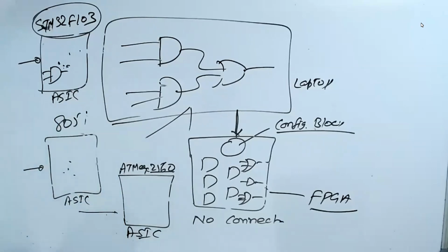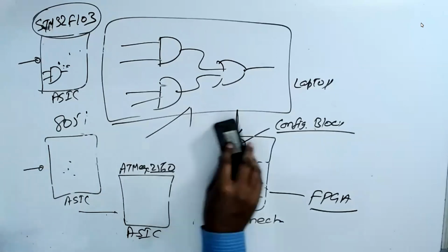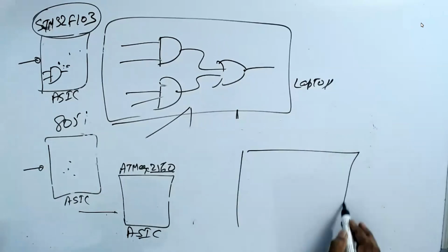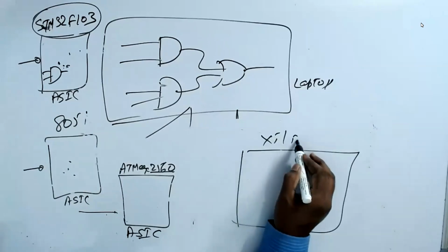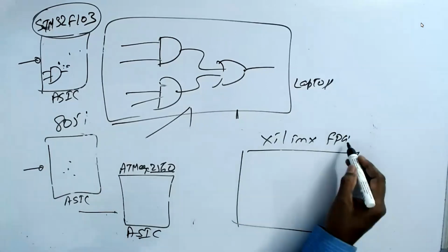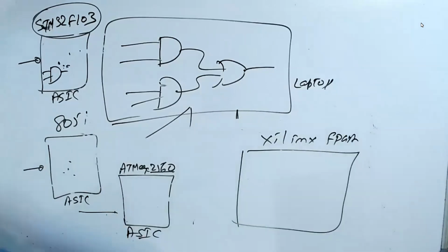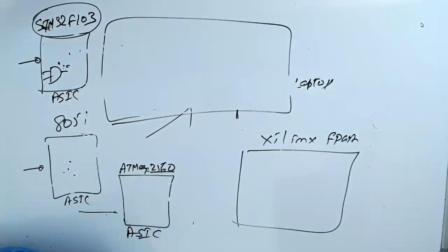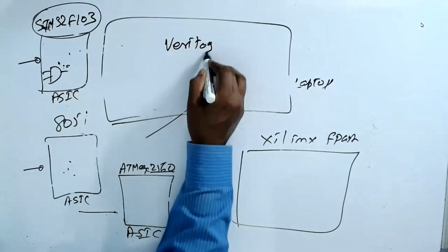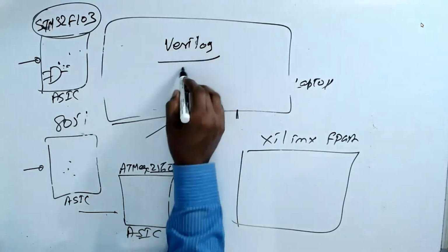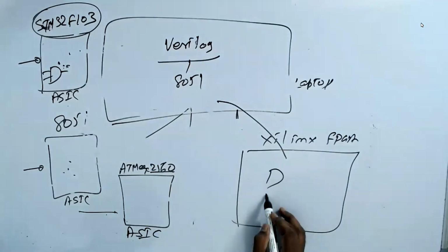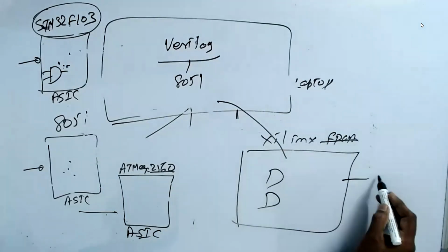But if I have an FPGA, think here. If I buy an FPGA, Xilinx Spartan, whatever series, and develop a Verilog code here, I can make a Verilog code for the 8051. If you download it to this, I make the connections, and this FPGA will become an 8051.